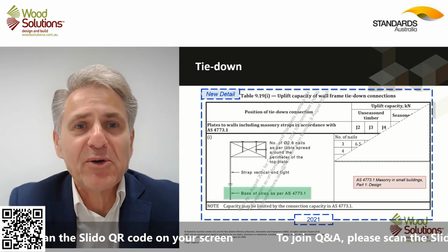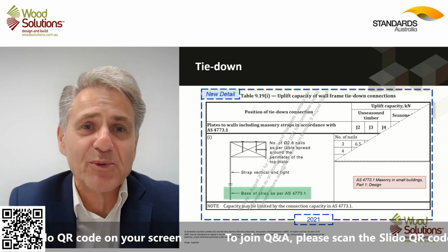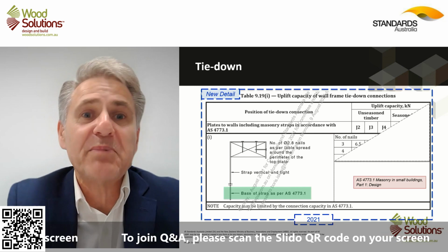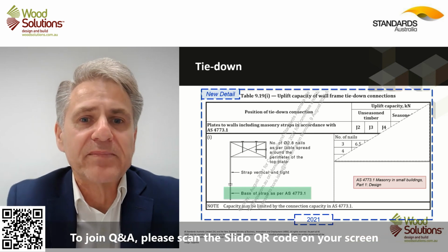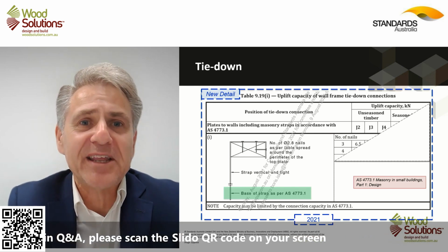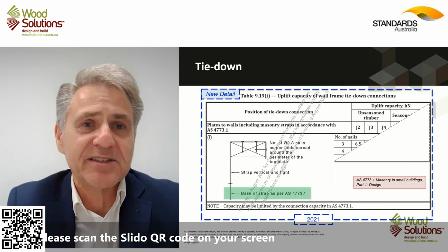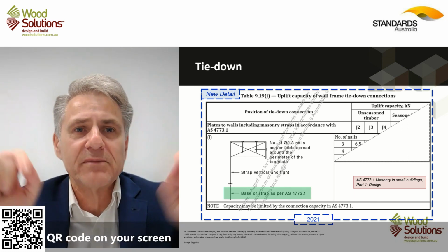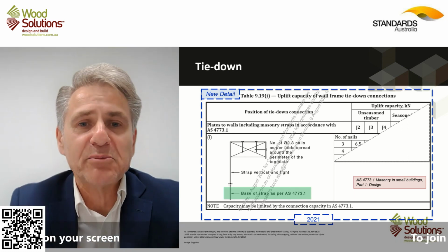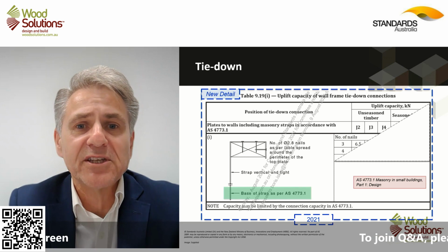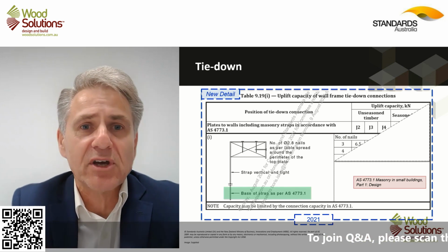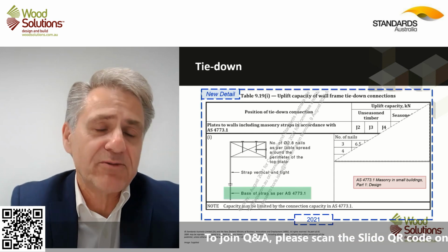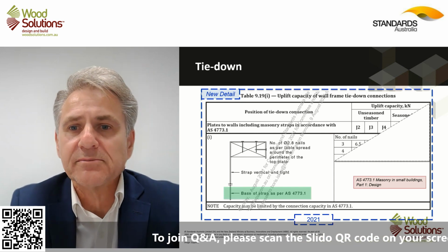And if you're wanting to know the capacity of the unreinforced or the reinforced masonry, you've got to go to the AS 4773 Part 1 standard. I've had a quick look at that standard, and there are capacities using a similar approach to what we use in 1684 in terms of the uplift load width detail and the tie down capacity. So you can basically equate the strap detail as shown on your screen and the capacity of the masonry, unreinforced or reinforced masonry systems.